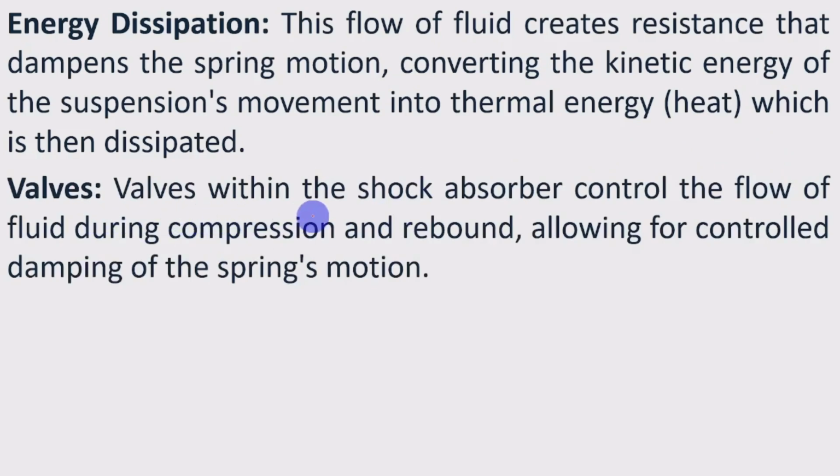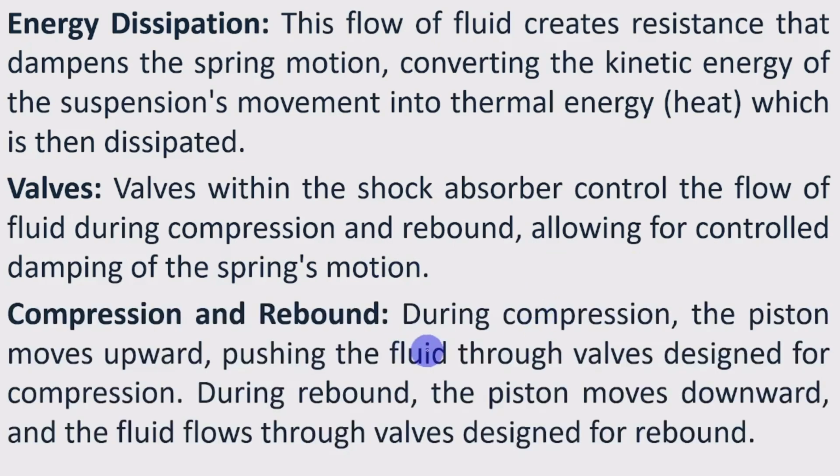Holes. Holes within the shock absorber control the flow of the fluid during compression and rebound, allowing for controlled damping of the spring's motion. Compression and rebound. During compression, the piston moves upward, pushing the fluid through valves designed for compression. During rebound, the piston moves downward and the fluid flows through valves designed for rebound.